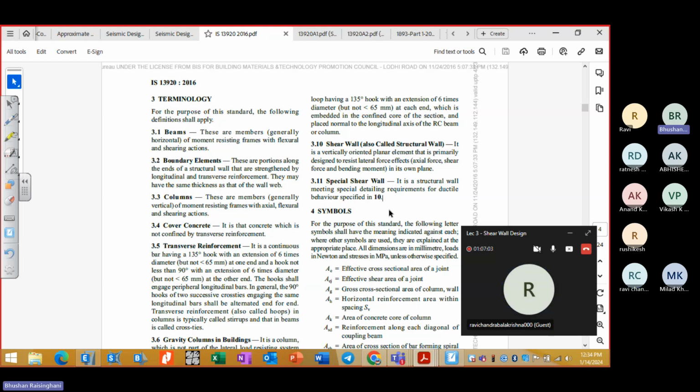Okay, sir. So we need to protect non-structural elements while we need to design structural elements. That is the difference between the two: if non-structural elements are getting some forces, we design them for those forces, and either we separate them out from the main frame. And if they are participating in lateral load resistance, we declare them structural because they will also transfer the forces. So we cannot break them after construction. Right, sir, because they will participate in resistance or under redundancy action. Yes, yes.